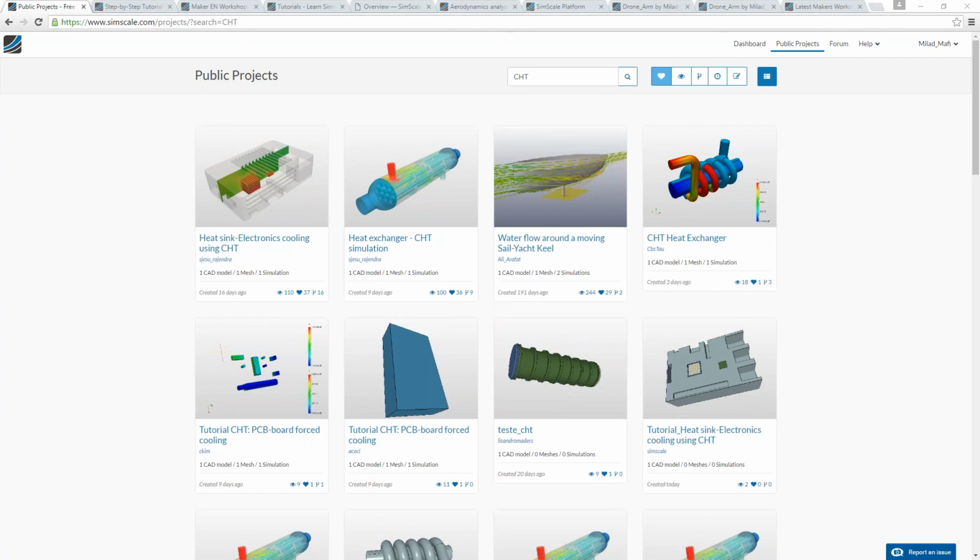First point is the model itself. If you want to use a model which is not considering plastic effects, and you want to simulate something like fatigue, then for sure this is a big problem for your accuracy. So you have first of all to choose the right model and the right assumptions.